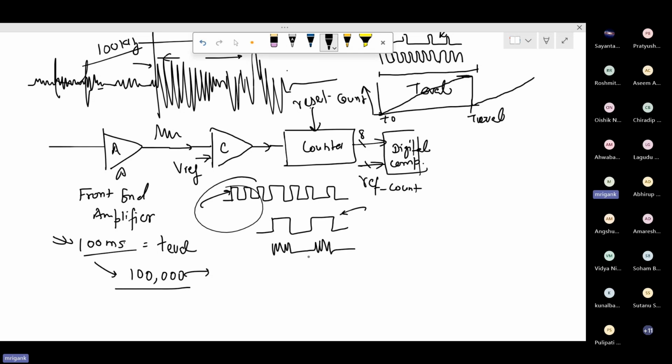Again, it is a parameter, a decision based on observance of the signal. We can decide how many pulses we need to count to reliably say that yes, it is a seizure signal. That is the signal processing part. Before designing the circuit, we need to look at the signal and apply the algorithm and check: in all these hundreds of seizure data that is recorded and reported, if I keep a count threshold of 1,000, is it giving me correct results for those hundreds of patients?